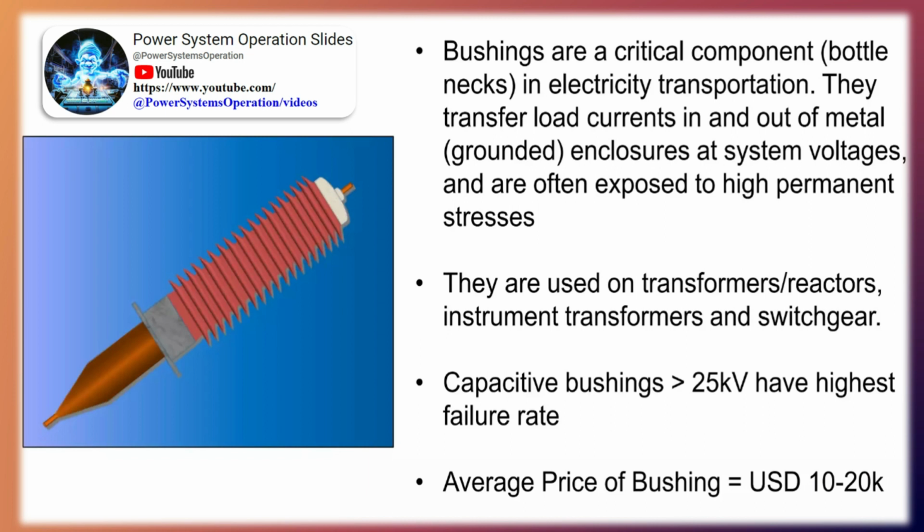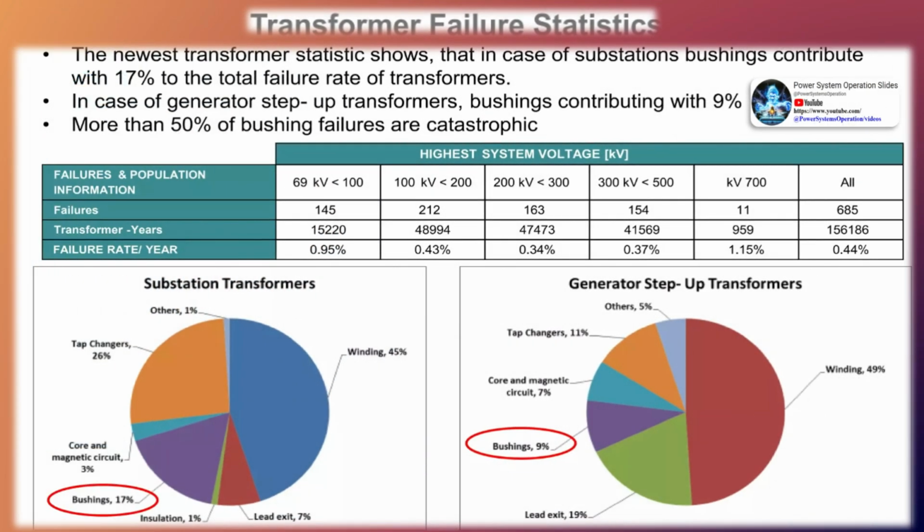Why bushing monitoring? Among the reasons for transformer outages, bushing failures are often the cause. It is common to find a bushing testing poorly, and there have been many noted total transformer failures due to bushing failures. One reason may be because bushings are often tested offline to measure capacitance, dissipation factor, and power factor.